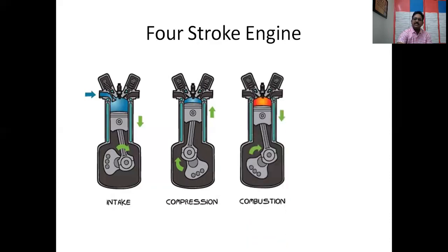Now the next one is the expansion stroke. At the end of the compression stroke, what happens for petrol engines? A small spark will be ignited by the spark plug. Because of the spark, the high-pressure, high-temperature compressed fuel-air mixture will burn. That's what happens for the petrol engine.